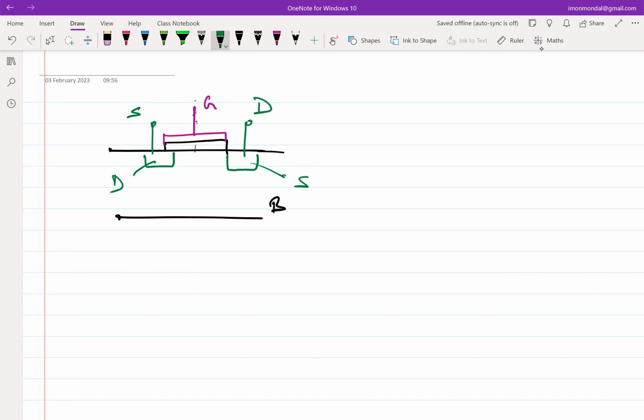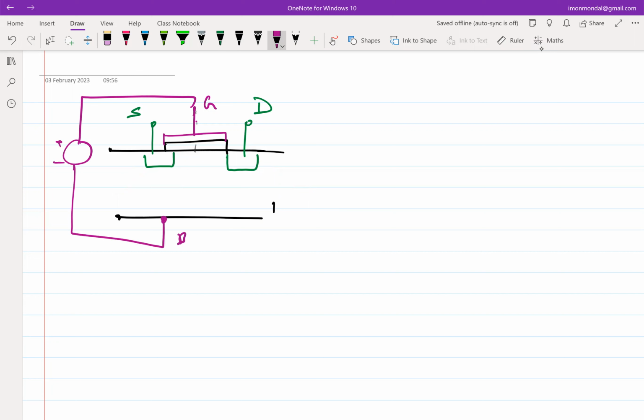No, body is also common to both terminals, right? It doesn't matter. What it says is that it really doesn't matter. It doesn't matter because ultimately, how are you getting carrier flow? So firstly, you'll have to obviously apply certain voltage between, let's say, gate and body. Then it creates some carrier in the channel.